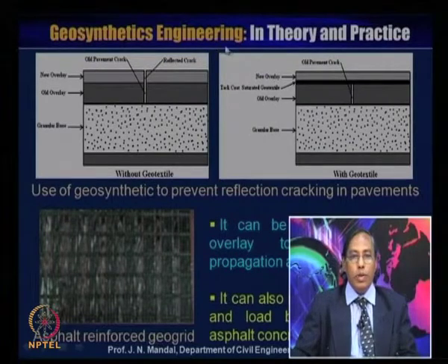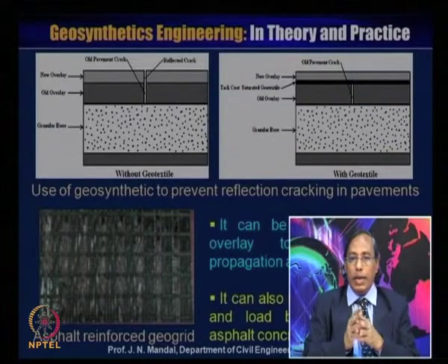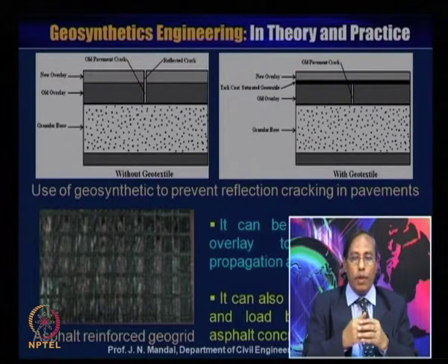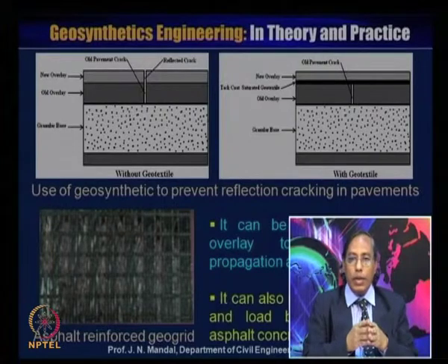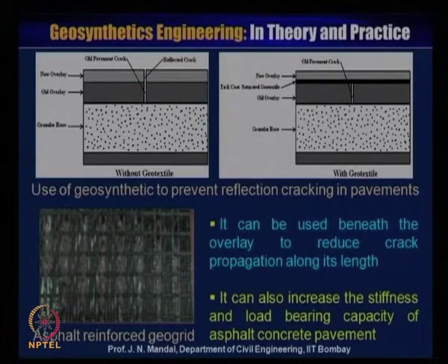So, use of geosynthetic material can prevent reflection cracking in the pavement. It can be used beneath the overlay to reduce the crack propagation along its length. It can also increase the stiffness and load bearing capacity of the asphalt concrete pavement.